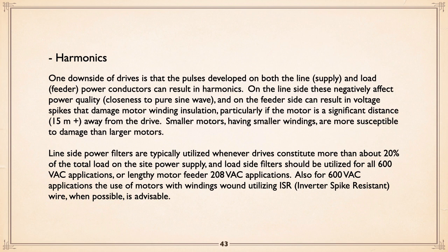On the feeder side, it can result in voltage spikes that can actually damage motor winding insulation, particularly if the motor is a long ways away. What's a long way? Generally 15 meters, so call it 50 feet between the drive and the motor. Over that, you really get nervous. Smaller motors, having smaller windings, are more susceptible. So the smaller the motor, as I say, the more susceptible it is to this.